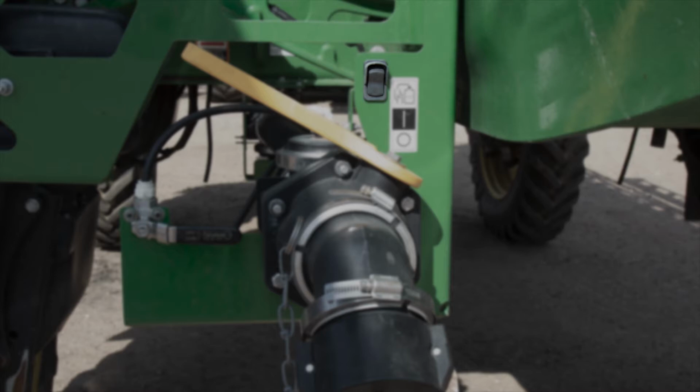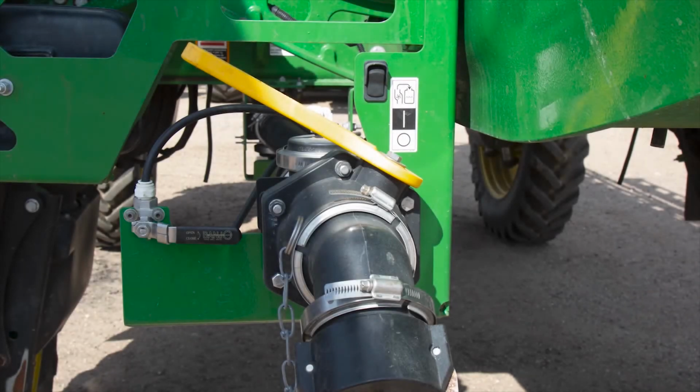Now if we wanted to pull product on using the sprayer pump, there's a detent position on the top side of that switch. We can just push and release it. It starts the pump up on the sprayer and immediately starts sucking product on. So when we talked about the automatic solution command system, this is where we could enable target fill, or the nice part about having the auto solution command system, there's floats inside of the tank. If it knows this machine, say we're looking at an R4038, it knows when that machine hits 1,000 gallons that it is full, and it'll automatically shut the sprayer pump down without any additional operator involvement.